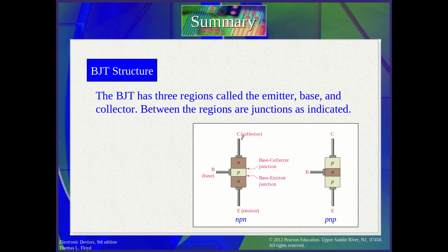For the PNP transistor, it is reversed: the emitter current comes from here and is split into a very small base current, and the rest of the current goes to the collector. So it is the same idea. Here you see the direction of the emitter current. If I draw this symbol, it means I use PNP; for an arrow out, it is NPN.